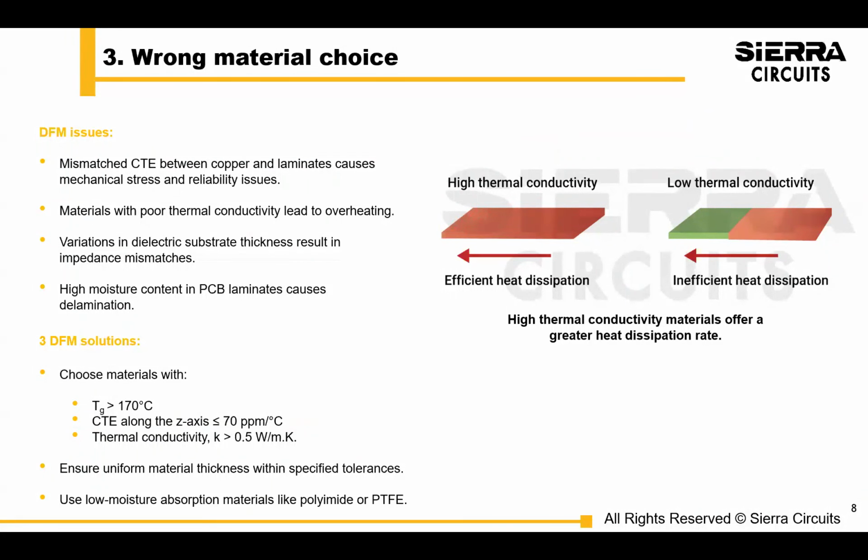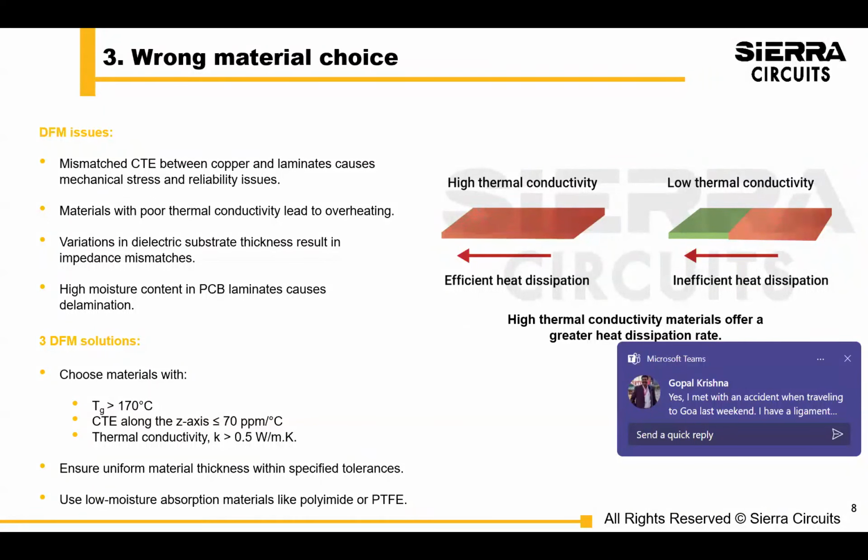So we're highlighting areas that maybe you're not looking at, which are just as important as the electrical properties of the material. So the thermal conductivity of the material, the CTE of the material, all these things are really important. And if you're not picking a specific material, we would pick a material that is consistent in X, Y, and Z as well.